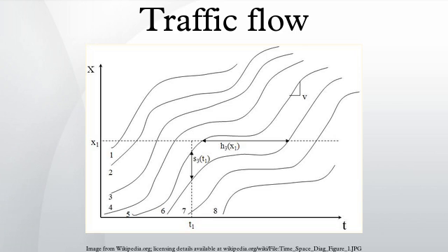When congestion occurs on the highway, it will extend the delay time in traveling through the highway and create a longer travel time. Under the user optimum assumption, the users would choose to wait until the travel time using a certain freeway is equal to the travel time using city streets, and hence equilibrium is reached. This equilibrium is called user equilibrium, Wardrop equilibrium or Nash equilibrium. The core principle of user equilibrium is that all used routes between a given OD pair have the same travel time. An alternative route option is enabled for use when the actual travel time in the system has reached the free flow travel time on that route.